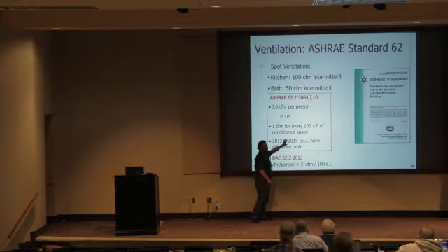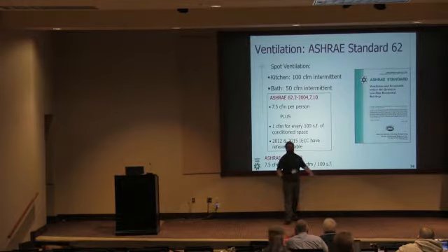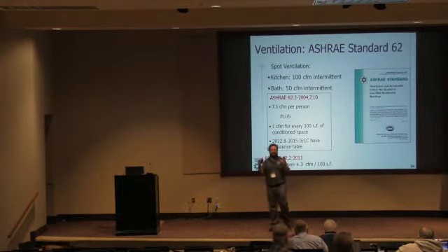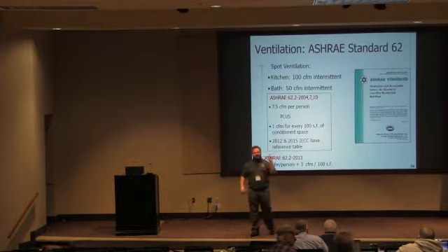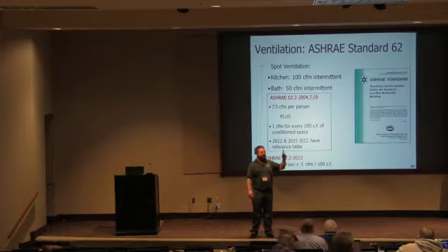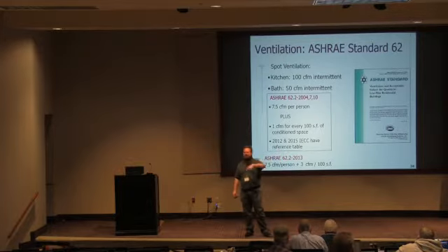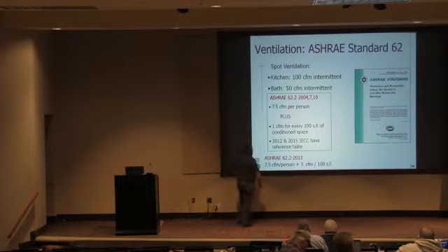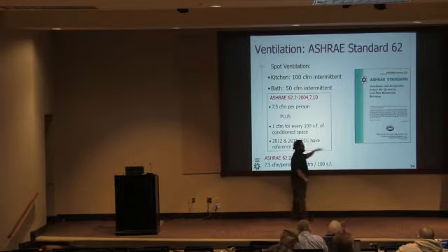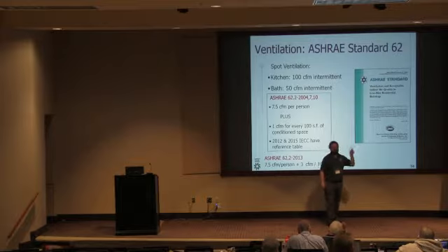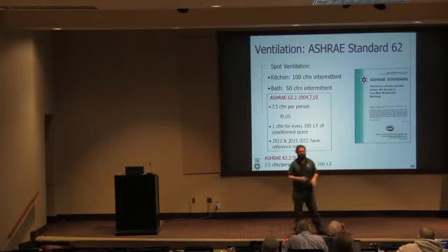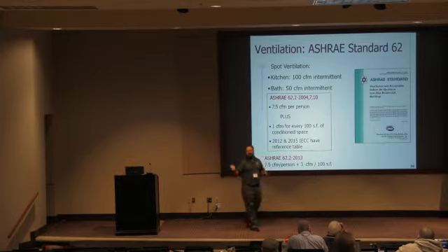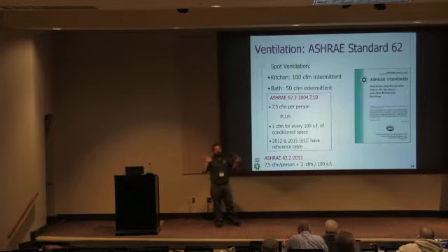And the 2012 and the 2015 IRCs have a reference table written into them because they both say mechanical ventilation is required in all new homes. There's no more, if you test and if it's this tight, then you have to do ventilation penalty. No. 2012 and 2015 IRC say, IECC and IRC say you have to do ventilation in new homes. So we've eliminated that confusion about how tight is too tight, and then I have to do ventilation.